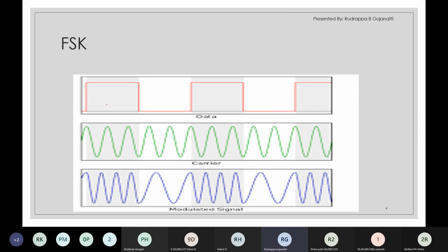So here they are representing that logic 1 is represented with high voltage for the entire bit duration, and logic 0 is represented with 0 volt for the entire bit duration. So it is actually non-return to zero unipolar format. So here what happens is only two possible values, that is 1 or 0. Therefore, only two possible voltage representations. That is, it will be either plus V volts or it will be 0 volt.